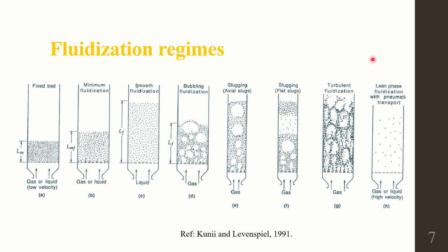So in such cases, we need to keep a recirculator so we can collect the escaping solids and recycle them back inside the bed. At a certain height we would have a recirculation cycle where we take the solids escaping from this and pass them back into the system. So these are all the fluidization regimes commonly observed in fluidized beds, depending on the velocity at which we are passing the fluid. The major influencing factor here is the fluid velocity. So that is the fluidization regimes.